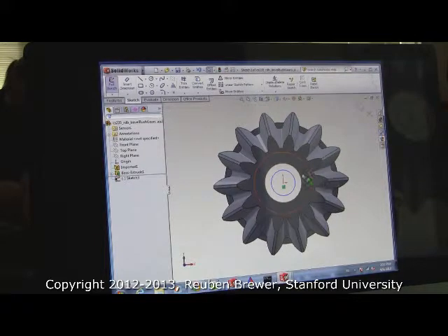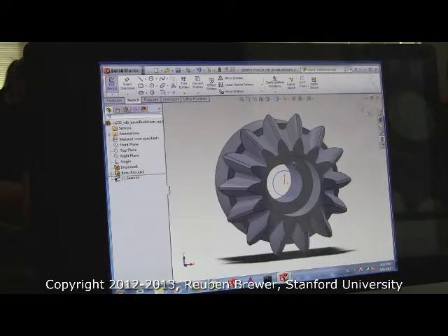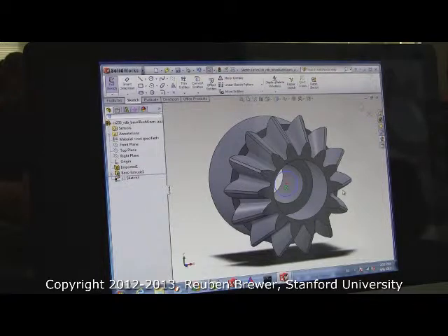So let me just tell you what we're doing real quick. Don't rotate your part, but I'll show you what we're doing. Basically, we downloaded this gear model, and it had a bore of like 12.7 millimeters or something, or it had a bore we didn't want, so we had to change that bore. So that's why we're going through all of this, to make that bore, that central hole, the size we want. Now, we set the original bore to 8.1 millimeters. I could dimension this second hole to 8.1 millimeters. Does anyone know what the problem with doing that is?